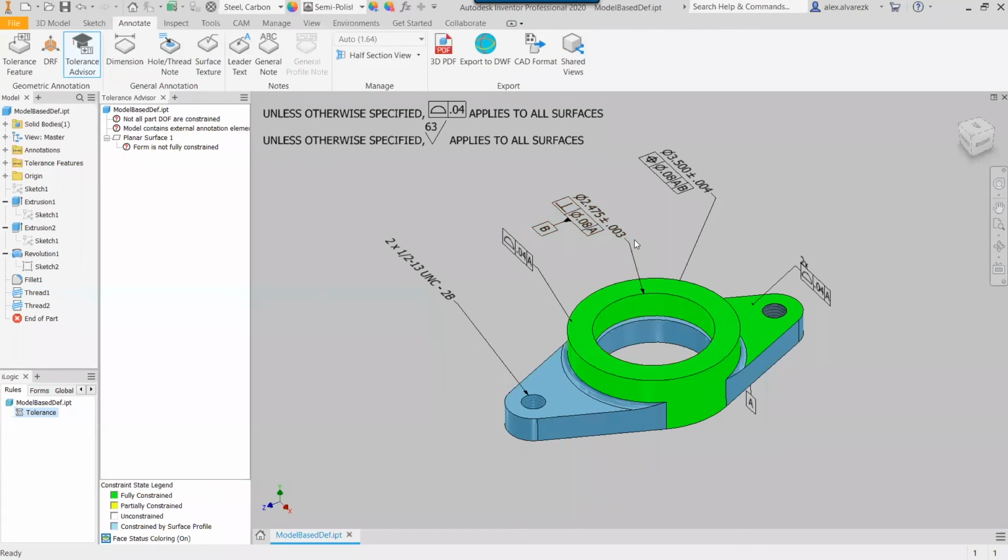Okay, so essentially, we probably still need a little bit more information to get some sort of manufacturing model for this. So you would want to go ahead and add that to a 2D drawing and add anything that you guys missed. Nice thing about this too is that you can actually promote some of these dimensions in the 2D drawing space. So you don't need to start from scratch. You can automatically promote some of these annotations, and they're going to show up in the 2D workspace.